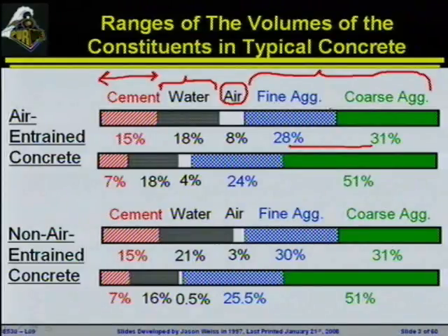It's also going to be a mix that's likely going to be expensive, up to a mix where we may be looking at something like 76, 78% aggregate. So you'll notice that the aggregate is a fairly large portion of the overall volume of the system. The aggregate's going to be in there really for two reasons. The first reason, which is a very practical reason, is the aggregates are going to help out with the economy of the overall system. Aggregates are going to be much cheaper than a lot of the other components in the system, so the goal is really to try and throw as many of the cheap components in as possible. So try to fill up the volume with the aggregates because they're the least expensive.